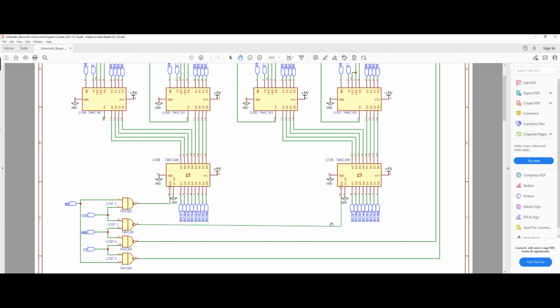We just bring that line low, and that basically outputs the content of the transceiver on the bus. However, as you can see here, we are actually combining that counter out signal with a HI signal, or with the inverted HI signal. And we are feeding those into a 74HC00, which is basically a NAND gate.